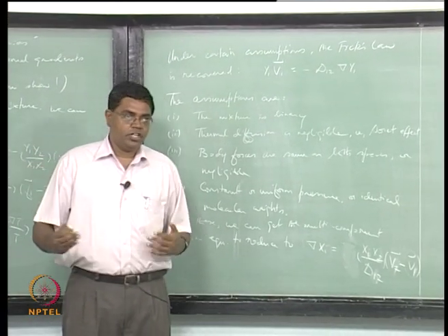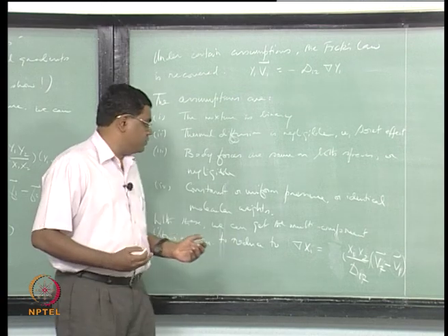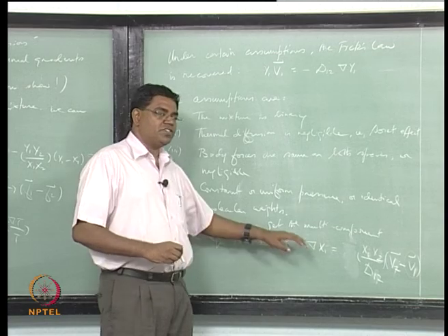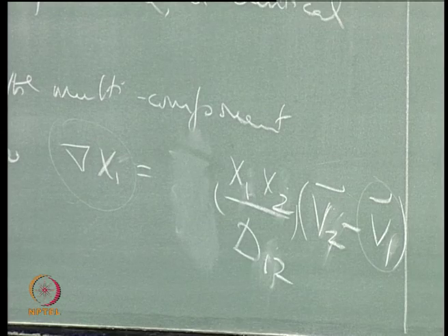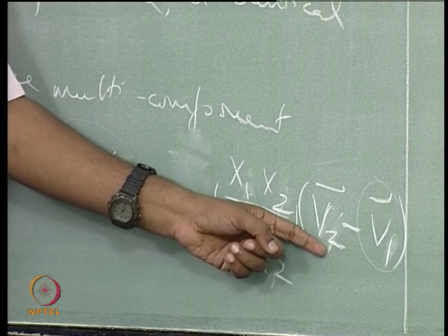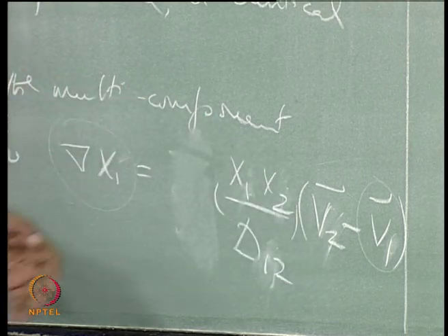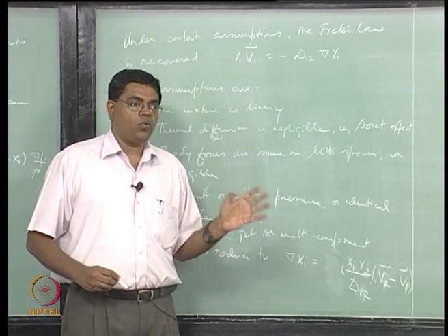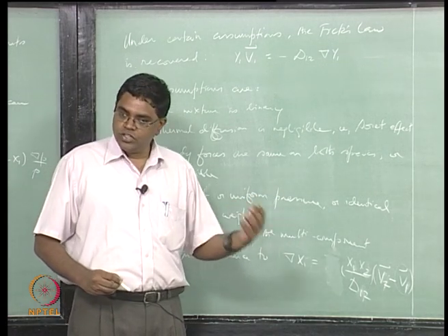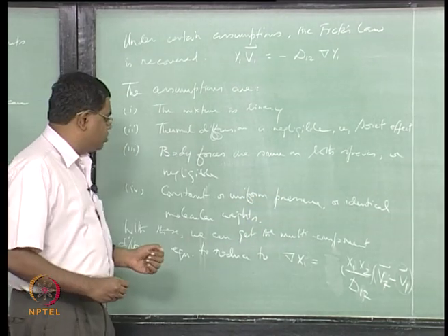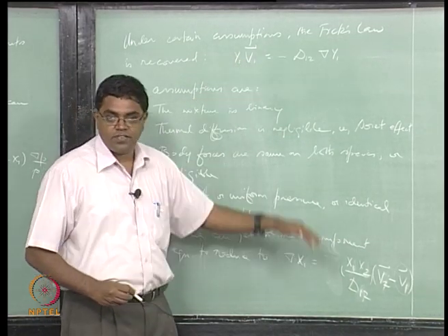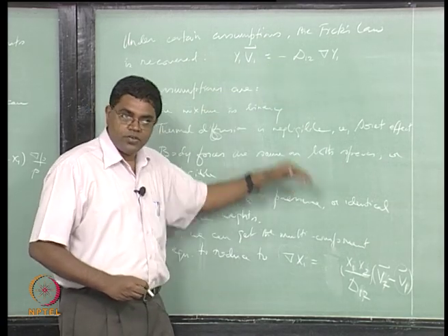There is a relationship between x and y for each species, which involves all other species, unfortunately. But this is a binary mixture, therefore it should be possible for you to figure that out. You also have to eliminate v2, which means you will have to consider the next equation and so on. Keep in mind, in a binary mixture x1 plus x2 is equal to 1 and y1 plus y2 is equal to 1. You should use those additional equations, and then simplify this to something like this. That's an exercise for you to do.